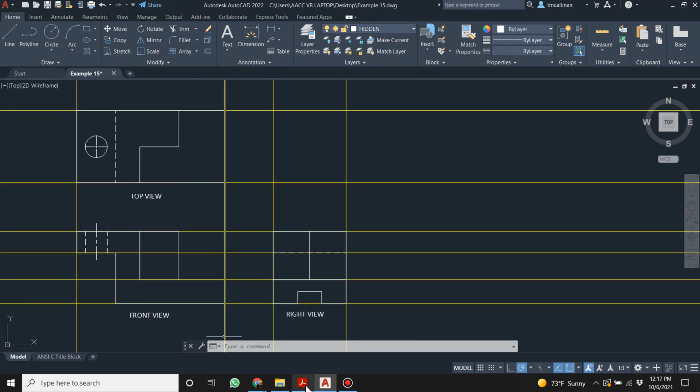Now what size is the circle? It's diameter 9. Now I'll show you a trick. Because I went up 20 here, there's 20 inches between that view and there's 20 inches between that view. If the spacing between those views is equal, you can do this trick. I'm going to project a 45-degree line up, and I'll show you. A for angular, 45, like so. And I can project stuff from this over to this 45-degree line and down.